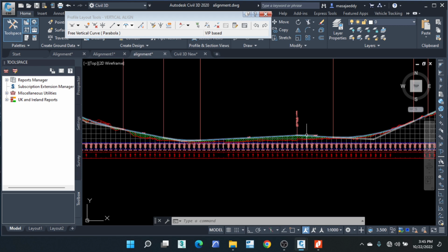For a short road, you can compromise with the largest region. If it's more in a rolling terrain, you apply the parameters for rolling. But if it's a long road, maybe 100 kilometers plus or even 70, you can separate your road into those three sections, and you design each section according to the parameters for that type of terrain.